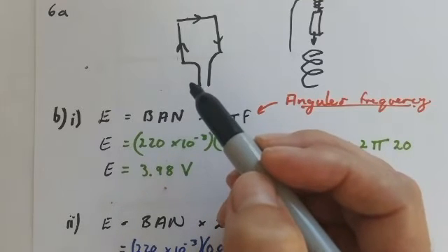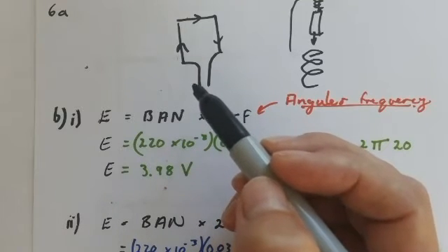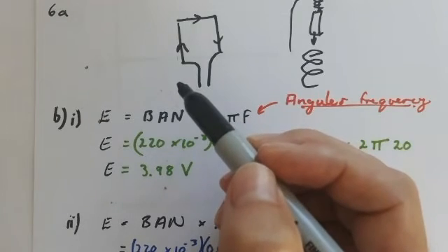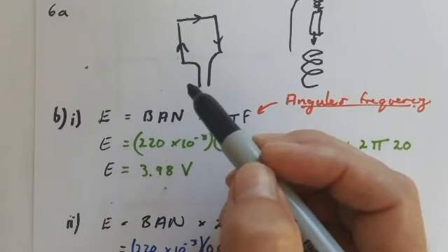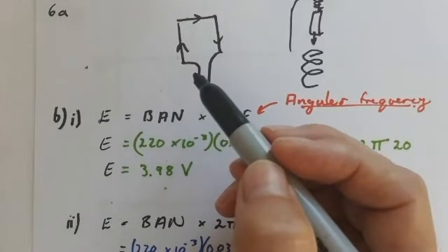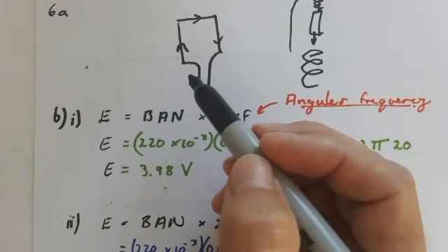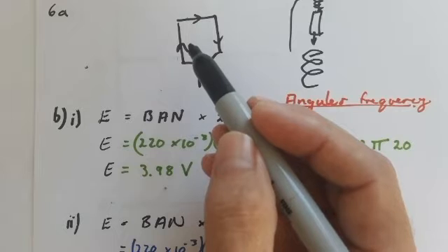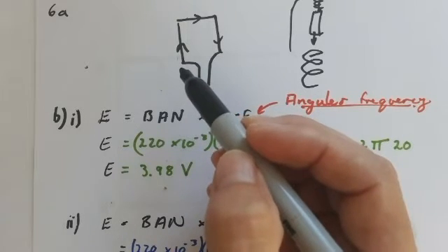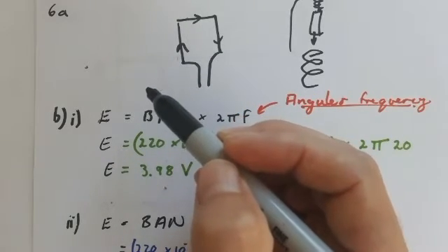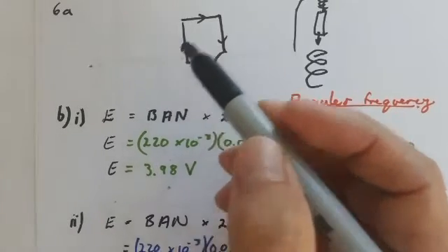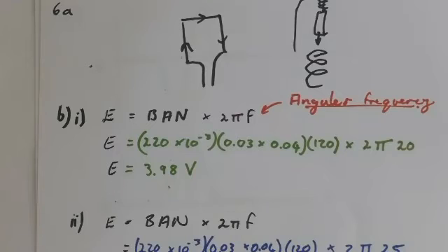But the word eddy currents doesn't occur anywhere in your textbook, neither in your syllabus. But I think it's worth it. They could definitely, they should accept it and will accept it. So a good way to state that is when there's current flowing, eddy currents are produced within your coil that give resistive forces against the turning of a generator. And those resistive forces will be absent when there's no current in the generator or in the circuit.